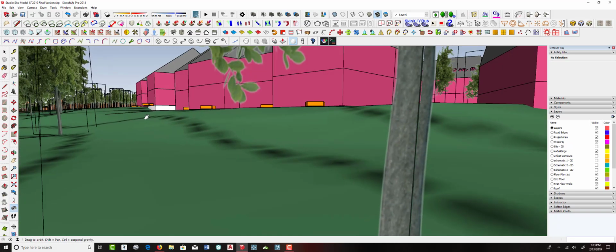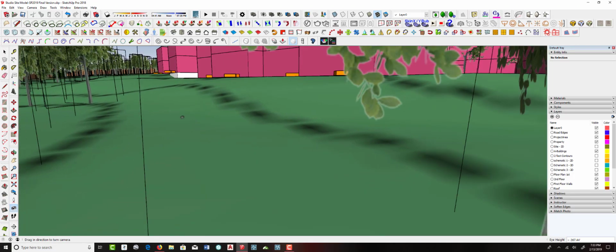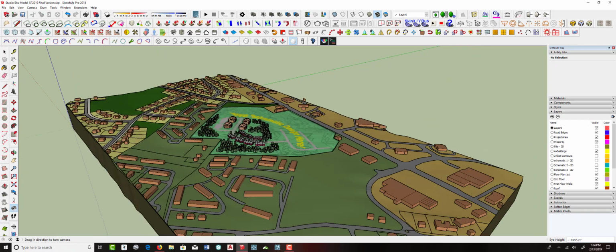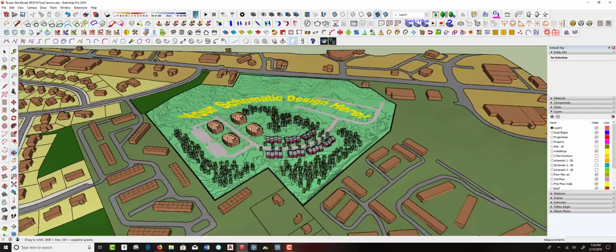Artisan works. That's giving you a really quick way to adjust landform, to put level building pads, and how you can place trees really quickly with scatter, and whether you're using scatter trees or Lumion trees, that's kind of up to you. But it gives you a really quick way to go in and create a really usable visualization of your design that includes all the three-dimensional information, just the grading, and then if you wanted to go in later, you could actually generate contours from that and see what that looks like. So that's the process I want you to go through.